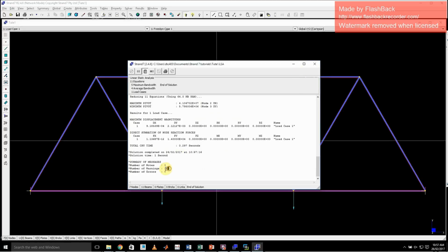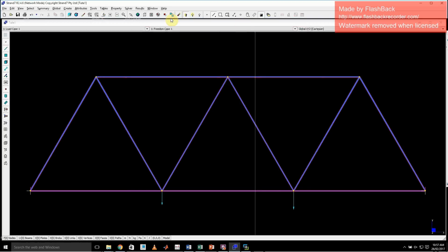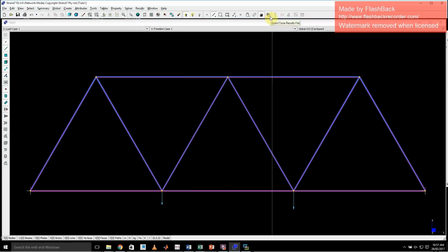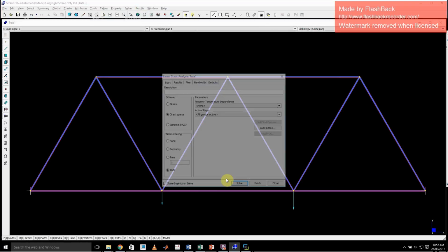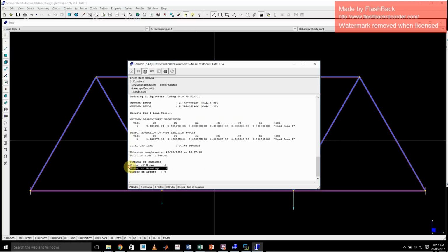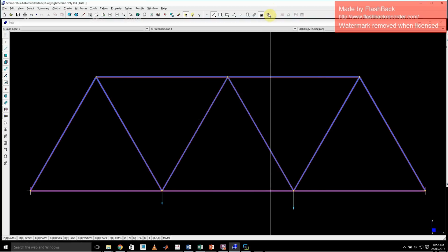Great. Warnings you will get, that's okay. Errors are not okay. If you get errors, that's very bad. It means generally that you've missed a property somewhere. You haven't filled in a geometry or a modulus or something like that. Or you had, say, beam property type 2 in here. Or you haven't restrained your model properly. Alright, so if you ever get warnings, don't be super worried. If you get errors, be very, very worried. Go back, fix your model.